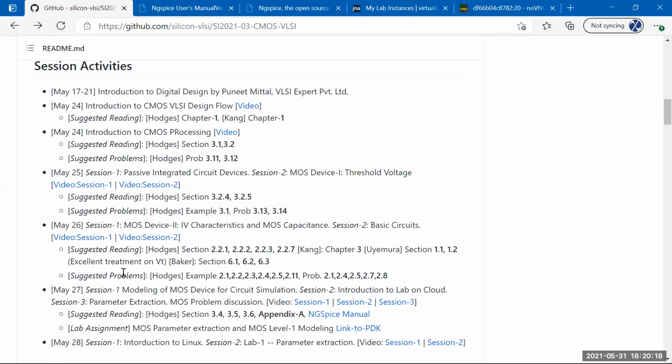Take the problem statement, because in the problem statement I've also given the PMOS. I've also asked you to do short channel, like reduce the channel length to 0.5, and you'll see this high voltage effect is even larger, right? We took a channel length of 1 micron to reduce the short channel effect, but you can still see the effect of it. Now you go to 0.4. Actually, this technology allows you to go to 0.4. Go to 0.4 and do the same thing. So go through the entire exercise and create a nice document, like a 3-4 page document, put it on GitHub, and it'll remain with you forever.